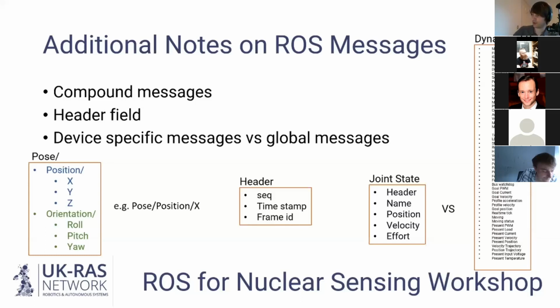Some of this is important, but there aren't many other nodes that need all this information. In ROS, really what we want to talk about is the state of the joint. So at what angle is the joint? That is conveyed with a so-called joint state message, and you can see a joint state message is only 5 fields. It's literally 10 times less stuff being moved around.